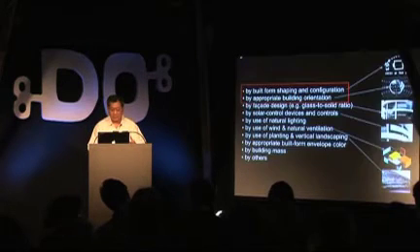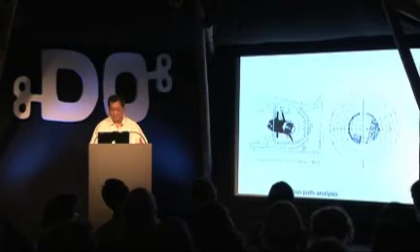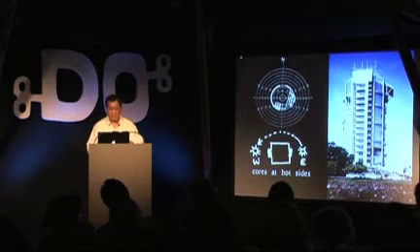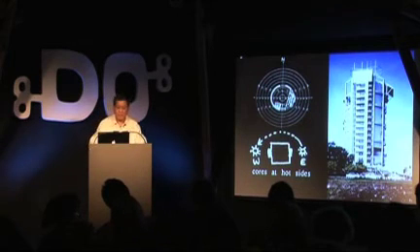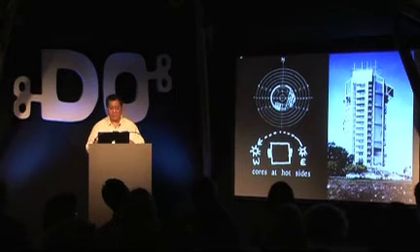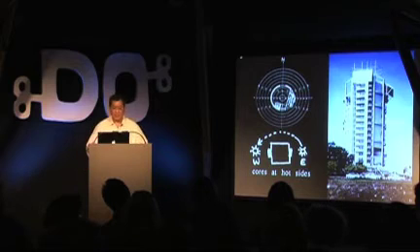Here's a building that we did about maybe 15 years ago, and we shaped the building and configured it in relation to the sun path. We look at the sun and we said, well, the site is about 2.9 degrees above the equator, and the sun is almost east and west over the whole day. So we put the core, the elevated core, on the hot side of the building on the east side, so that as the sun builds up during the day, it keeps the sun away from the usable spaces.